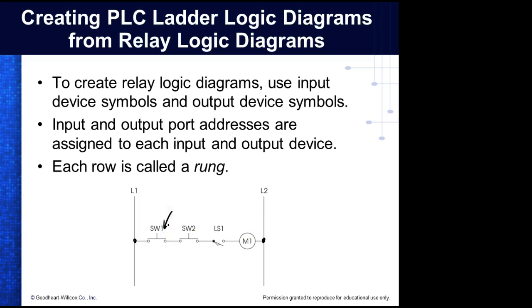So what's this symbol for? Well, you got to look real careful. This guy didn't draw it right. If it's above, so he should have put a bunch of space there. If the push button is above, it's normally open. If it's below and it's got to touch the dots, this is normally closed. So notice these are above. It's just really hard to see the space. This guy is really close. So these are push buttons.